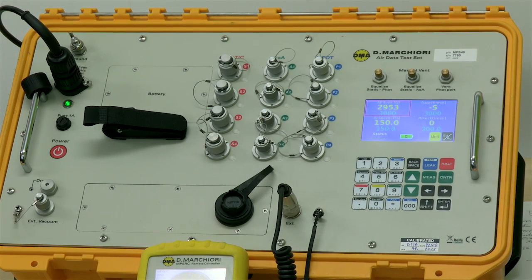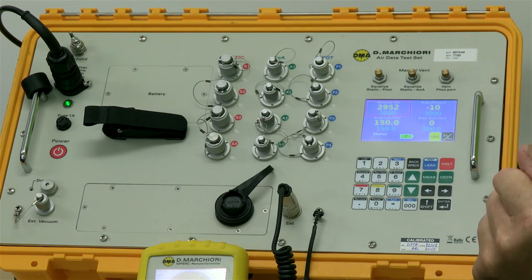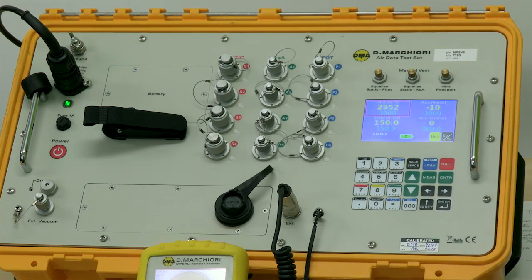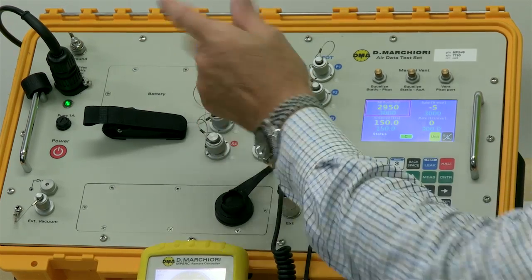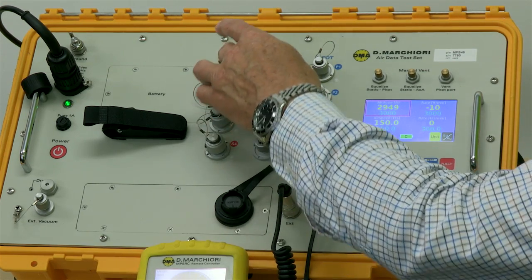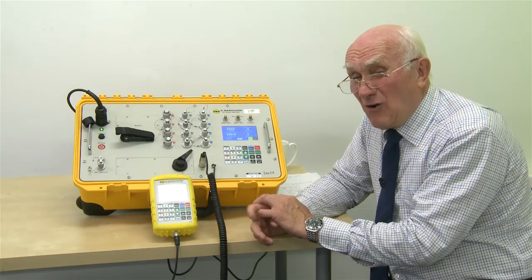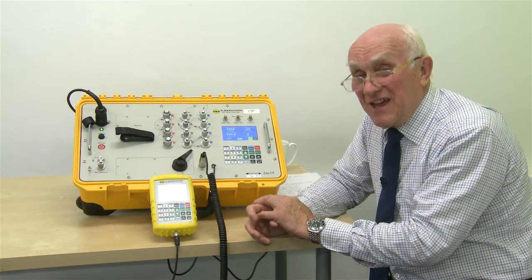Okay, we showed a few moments ago of how you can go into the leak test mode and then see what is happening to the aircraft in terms of what's on the static and the pitot. However, we've already pointed out, many people prefer to buy multi-port so that they can cover the individual pneumatic ports you're using. For example, captain, first officer, standby, etc. People like to be able to then examine what is happening across the whole range, and indeed find out where the leak is, if there is a leak.